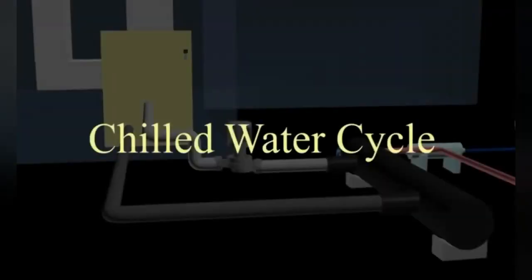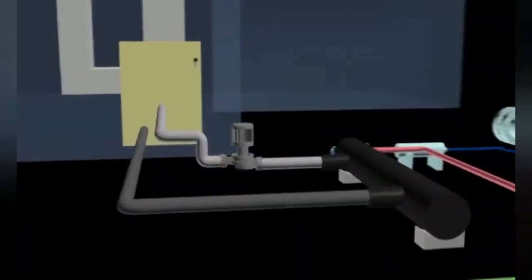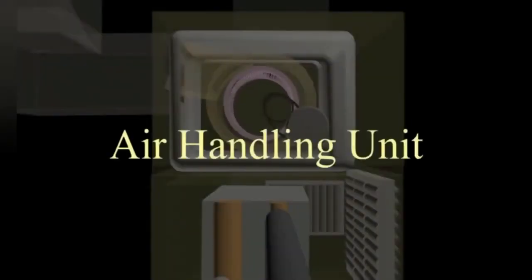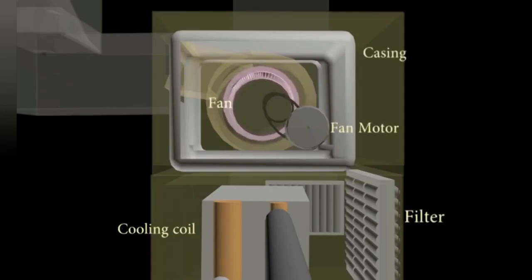Chilled water cycle. The chilled water cycle consists of two basic components which are the air handling unit and water pump. Air handling unit. The air handling unit is a place where cold air is produced before it can be distributed. It consists of several key components such as cooling coil, fan motor, belting, filters and the casing.